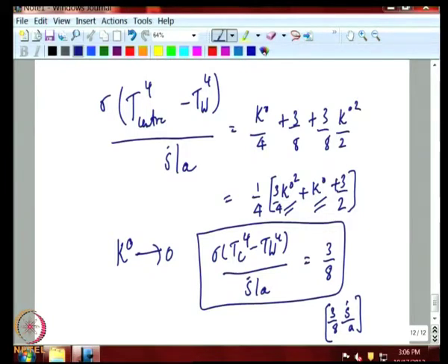And again, one sees that the temperature difference between the center and the wall is proportional to the heat released, which is not surprising, and inversely proportional to the absorption coefficient, which might look a bit surprising, except that once you realize that the efficiency of radiative heat transfer from the center line to the wall is partly determined by the absorption coefficient.